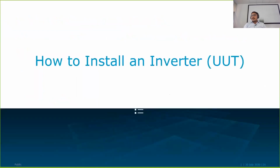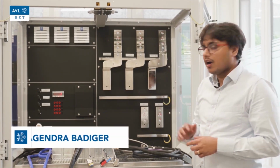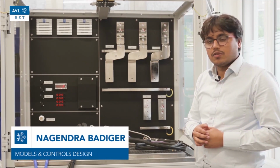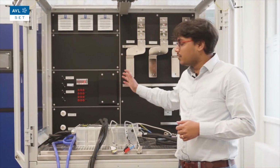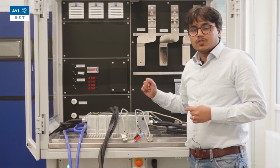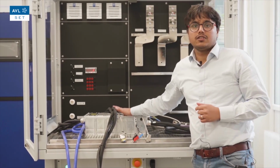now let's look in detail at how we can install this inverter in the inverter enclosure and make it ready for high voltage testing. Hi, in this video I will demonstrate how we can install a test inverter inside the inverter test table and make the necessary connections to the E-Motor Emulator on the high voltage side as well as the signal interface side, so that we can test this inverter with our E-Motor Emulator based testbed.